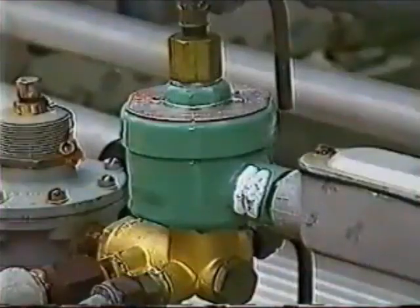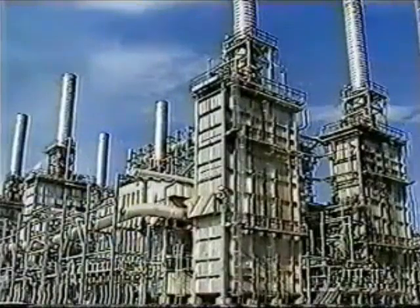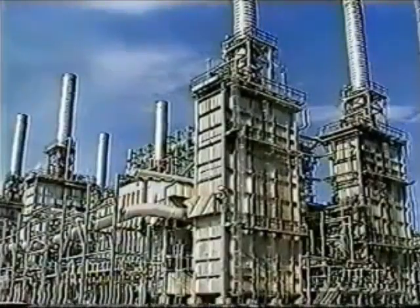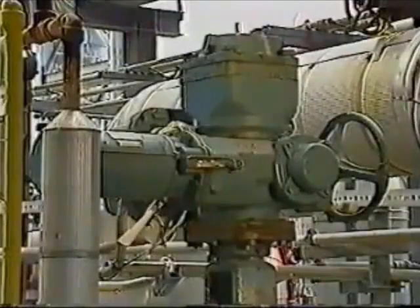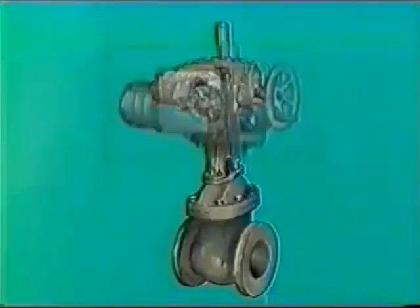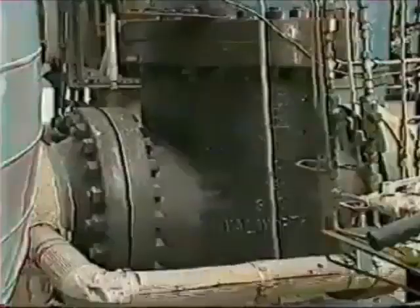Solenoid valves with heavy springs find important duty on fuel supply lines to boilers and furnaces where they snap shut quickly if electrical power fails or other safety trips are activated. If throttling action is required, a motor-operated actuator can be used to position the valve. The motor is connected to the valve stem through a system of reduction gears and is capable of moving the valve into any desired position.